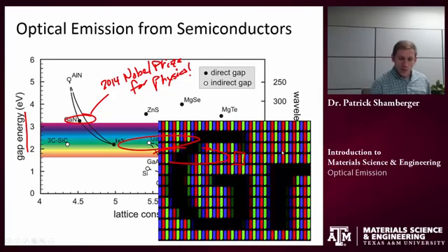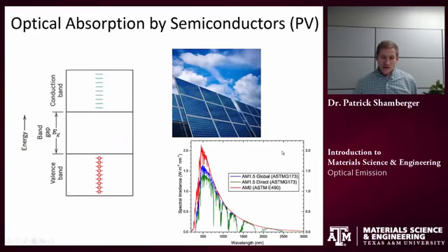But also, remember, blue has the highest energy of all of these wavelengths. So if I want to make a white LED, it's a lot easier to generate high energy photons and to maybe remove some of the energy of those photons, so we're able to emit across a broader spectrum, than it is to bump up the energy of photons. So gallium nitride is also behind any sort of white LED.